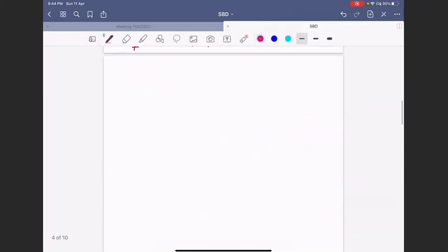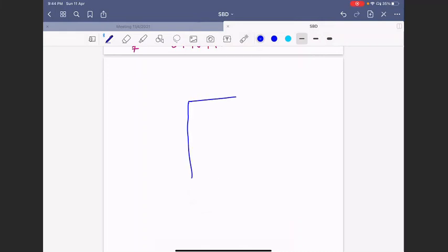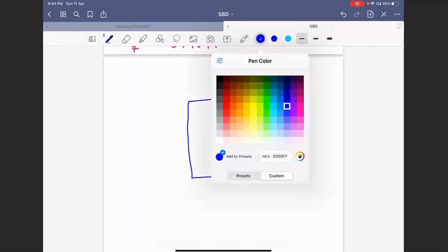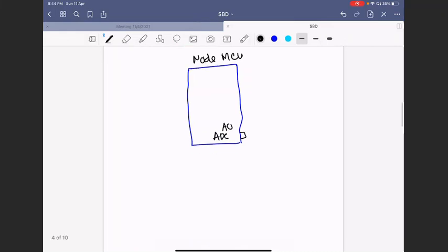Okay, let me give you a little bit of briefing about analog. What is meant by analog? This is your NodeMCU. Then this is the pin, the analog pin, ADC, or the name is A0. Now you put the potentiometer here, 5 volt, and then this one is the ground. This is the variable resistor inside the potentiometer, that's the symbol of the potentiometer.